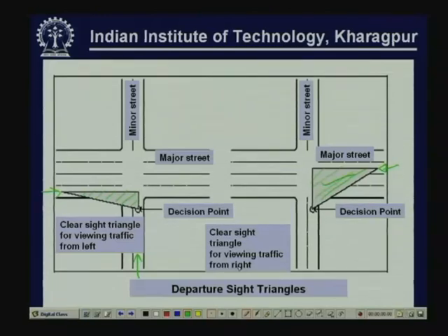So, remember that the movement we are considering is like this and like this. Okay? This is different from whatever is followed normally in India, but predominantly this concept is used in AASHTO. So, we are using the same convention that is followed in the AASHTO manual, but the concept can be applied in a similar manner for Indian operating conditions. The only difference will be that whatever we are defining as left turning would actually be right turning for Indian conditions, and whatever we are defining as right turn will actually be left turn in Indian conditions. That is the small difference one should keep in mind.